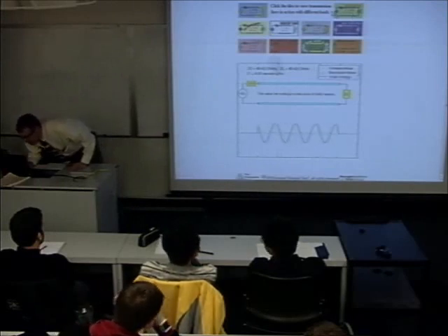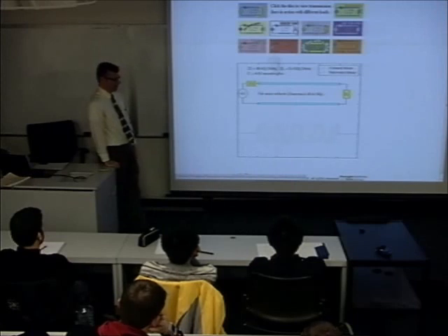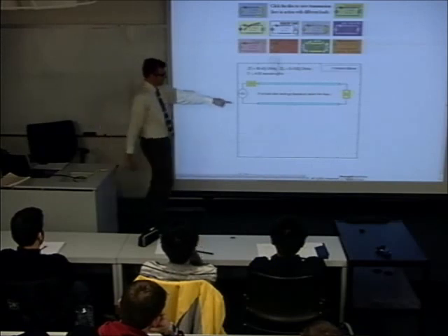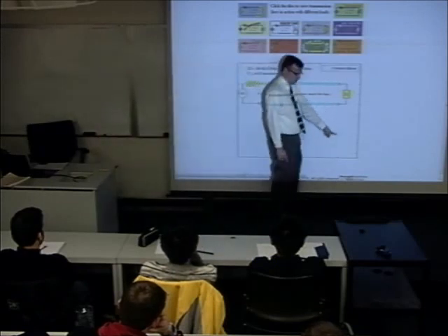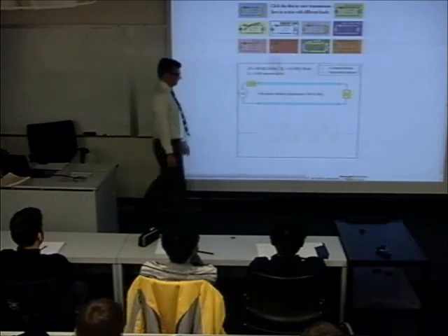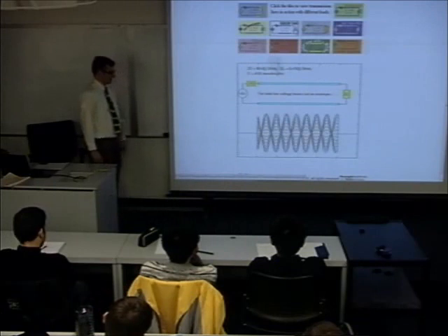Let's see, what about an inductor? What do you think that does? Forward propagating wave, backward propagating wave of the same magnitude, just like the open and the short. Makes sense. If there's a pure inductor at the end and no resistance, there's no place for the power to go, so it's all got to reflect back. But you'll notice it's neither at the peak nor at the short. It's something in between at the very end. The voltage and the current at the end of the line are not perfectly in phase or out of phase. It should be 90 degrees out of phase, right? Because it's an inductor.